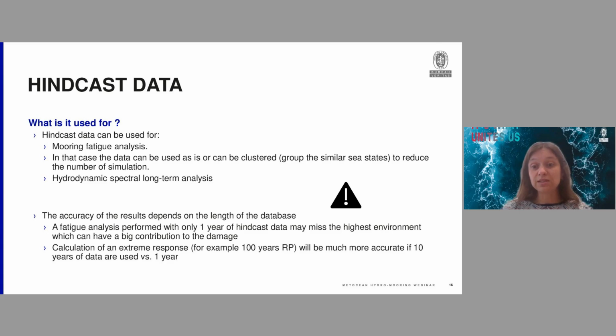You might miss the highest environment, which can have a big contribution to the damage on the unit. And if you want to compute an extreme response, for example, a 100-year return period in a spectral long-term analysis, it will be much more accurate if you use 10 years of data than if you use 1 year.